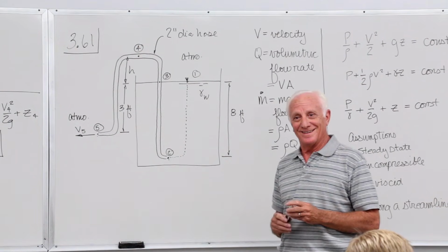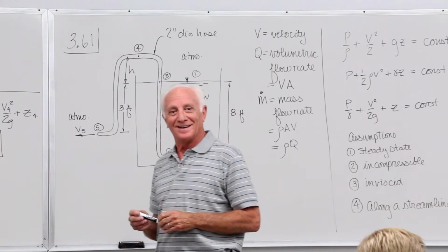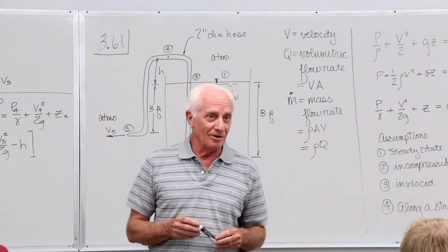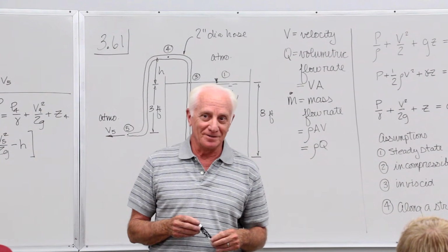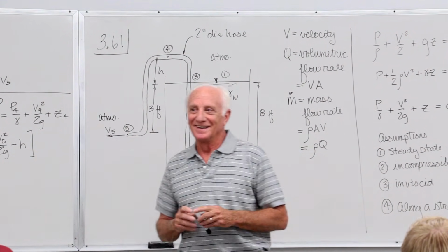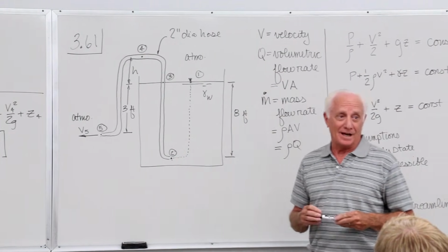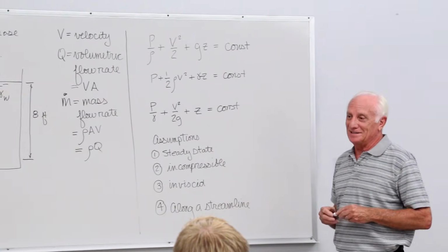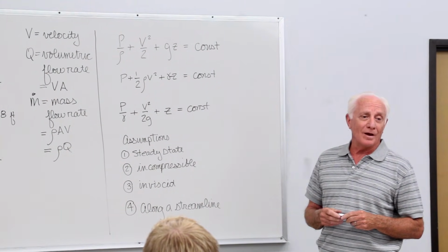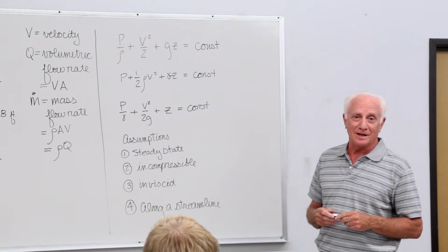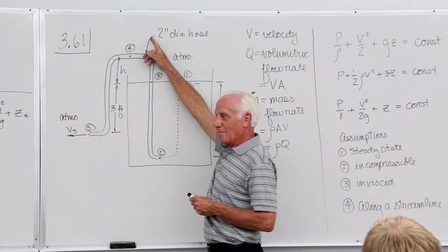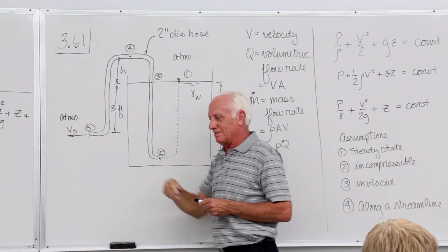Either low pressure or a high temperature. Oh yeah, high temperature can turn gasoline into vapor. Vapor lock: no more gasoline is pumped to the engine, and the engine stops. Up here, if you get high enough, guess what happens? No more pumping action, and water stops flowing out.